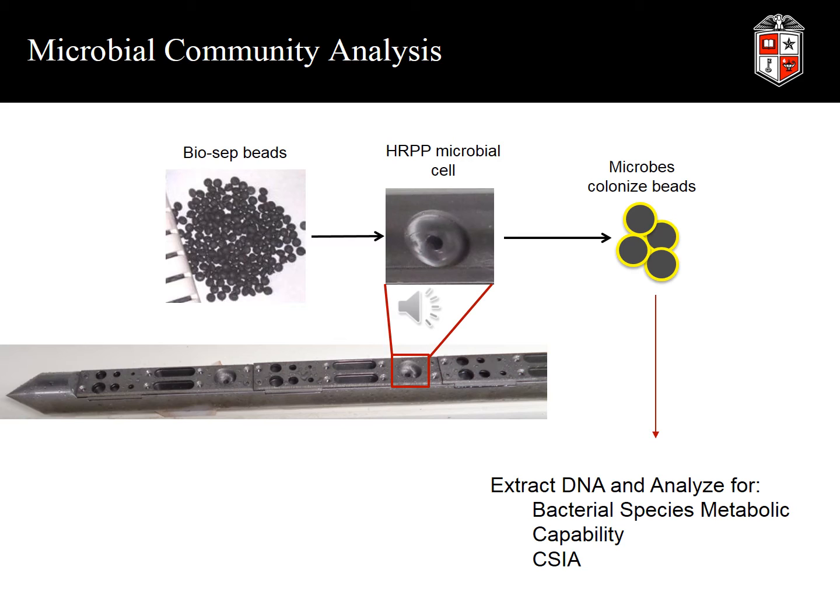The beads equilibrate with the bacterial community. Bacteria colonize the beads, and after a given amount of time, 2 to 3 weeks, the sampler can be removed, the beads are removed, and shipped to commercial labs for analysis. There's a very wide range of analyses that are possible. Molecular techniques can be used to evaluate the types of reductive dechlorinators, the relative numbers of dechlorinators, the types of bacteria that perform specific processes such as denitrification or sulfate reduction, or even have the capacity for certain co-metabolic processes.